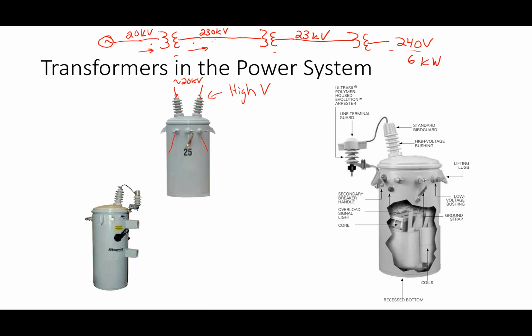Why did they go up in voltage and down in current? What's good about that? Yeah, because as I have a current flowing through this wire, it has some resistance. The losses in that are I squared R. So we want the I to be as small as we can get. Ideally, it'd be 0, right? They'd love to get it to infinite volts, right? But that doesn't make sense. Okay. You get as high as you can.